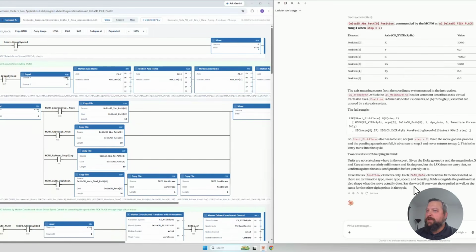So really big, like L85, is going to be multiple seconds in between reads if you're reading the whole program all at once. Basically right now what the Connect PLC does is it does a bunch of reads and gets a baseline for how long it takes to get through all of the tags. So it starts really high, like 20 seconds or something, and then after it's done that a few times, it kind of knows how long it should take. It lowers that value down to maybe double what it would take, or something. I don't remember the actual percentage, maybe 1.5, I think. Probably sounds better than double. And the reason for that is just so that we're not missing tags.